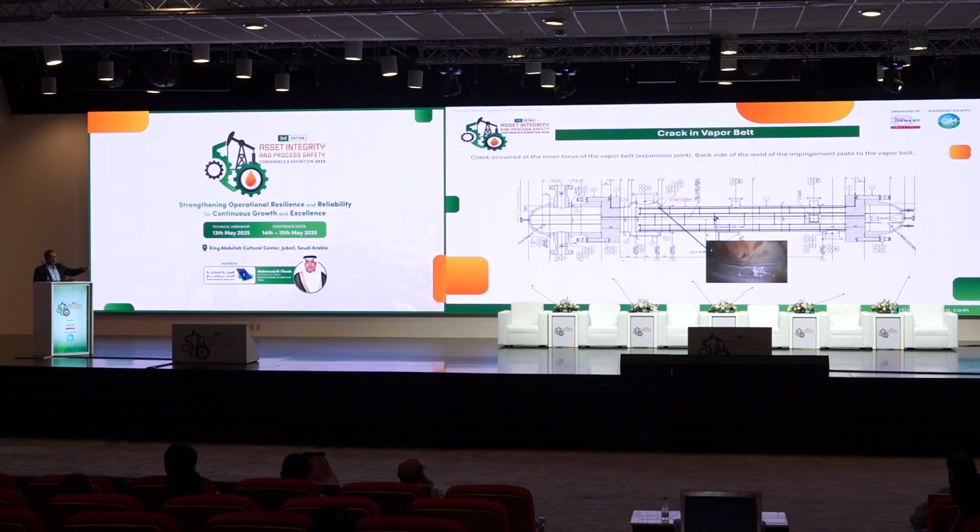And that's what we said, you can have some note in the code, for example, and if you missed it, like welding the impingement plate or the distribution plate inside the vapor belt to the high stressed area. This equipment, after only 1 year in service, started to crack.